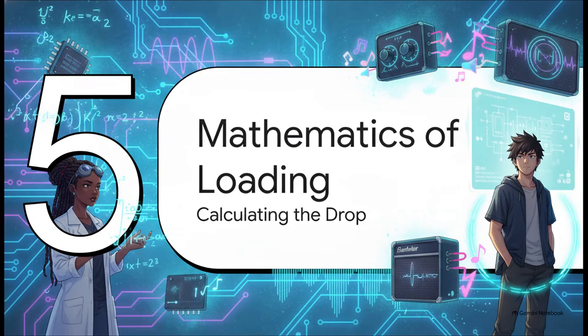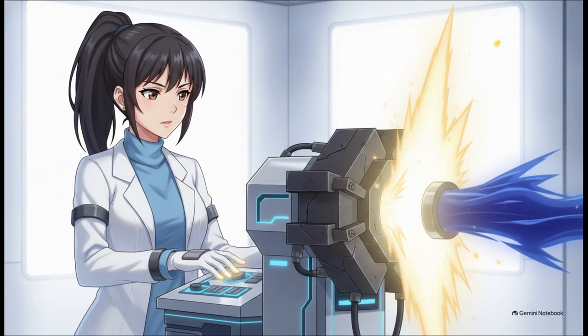Let's look at the numbers in Section 5, the mathematics of loading. Now let's explore how this general rule of energy transfer messes with the math of complex electronics, like amplifier gain, for instance. When you're designing an amplifier, the theoretical ideal current gain assumes a perfect short-circuit load. But in reality, an amplifier is terminated by finite non-zero values. The effective gain drops at both the input and the output. These specific resistor ratios that mathematically drag down your performance are known as loading factors. So the final real-world output you actually get is quite literally defined as the loaded gain. It's your ideal math, heavily taxed by physical reality.